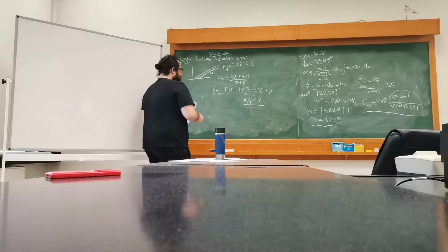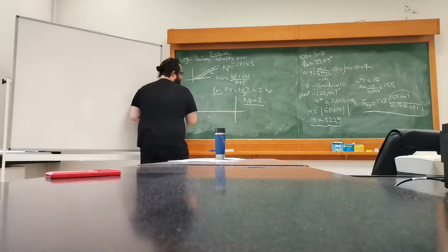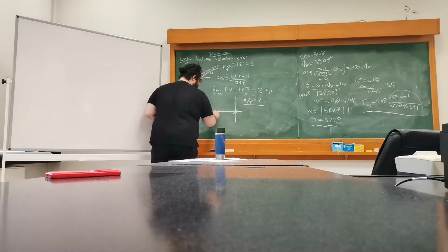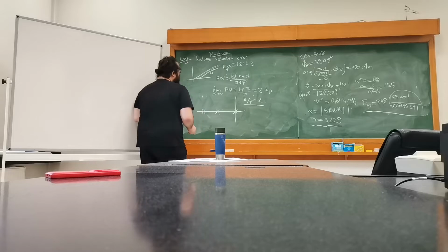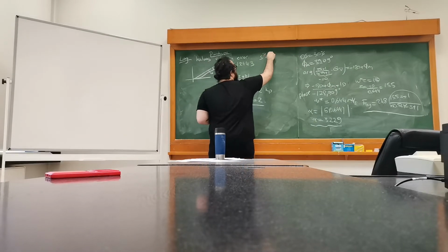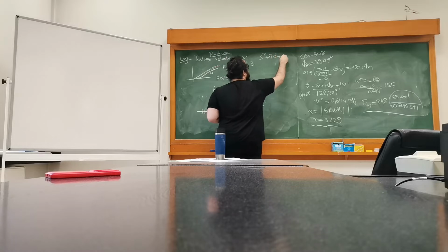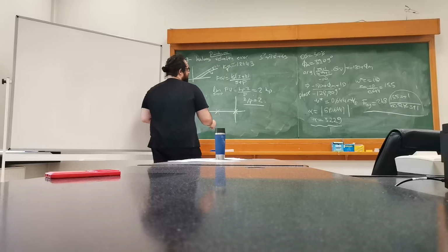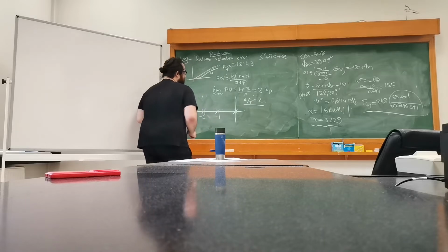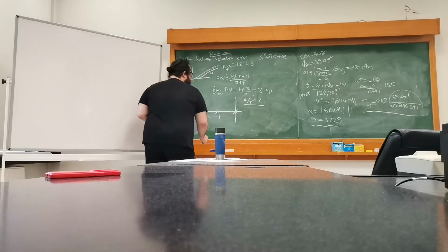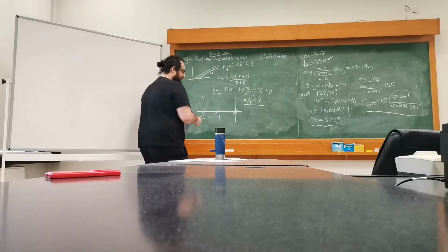Now, let's have the root locus here. What was it again? Let me just write that down. s cubed plus 7s squared plus 6s. So one at the origin, I guess minus 1 and minus 6. Yeah, it seems all right. And we have a certain zeta value.